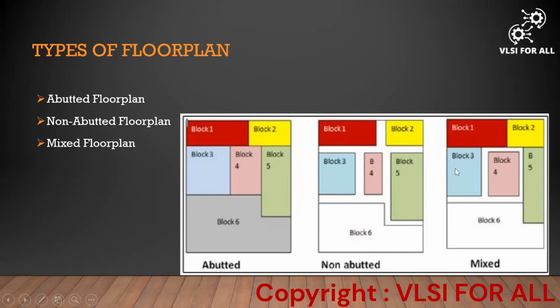And mixed means a combination of abutted and non-abutted, which means 2 or 3 blocks may be abutted and the rest of the blocks may leave some channel space. So that will be called a mixed floor plan. These types of floor plans are there. For our designs, while running the flow, we will get the information from the top level people.